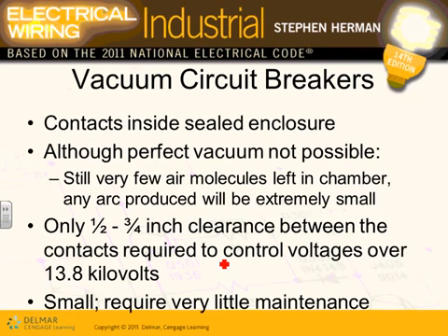The key point of our circuit breaker, guys: if you interrupt the short circuit, do you want to reset them and move on, or do you want to replace them? If you want to replace them, might as well put a fuse, right? Fuse, open, replace it. That's why when it comes to circuit breakers, it's a big deal. They need to live to fight another day after they interrupt.